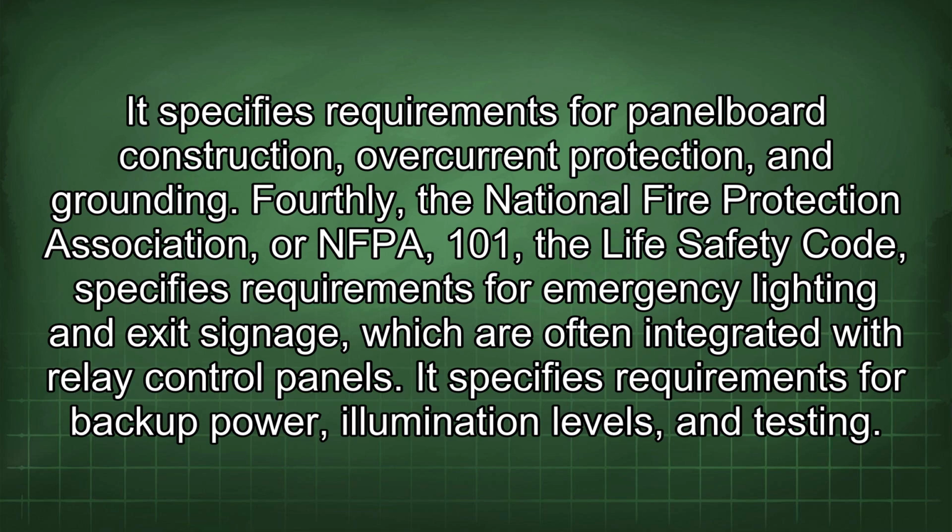Fourthly, the National Fire Protection Association, or NFPA 101, the Life Safety Code, specifies requirements for emergency lighting and exit signage, which are often integrated with relay control panels. It specifies requirements for backup power, illumination levels, and testing.